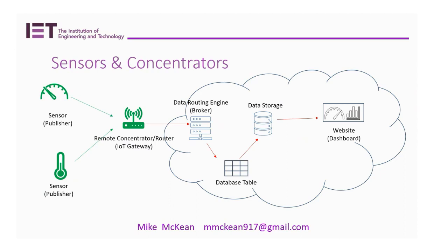Look it up in Google. What it basically means is that one of your devices is acting as a transmitter and using the cable as an aerial to transmit noise down that bus. And let's say, here's a typical problem. You're doing a project and you're installing 250 sensors in a big block of flats, and you go and install them all, and then you switch on your device here, and you've got humming coming down your line. That's a problem. The safe way is to install the gateway and install these.